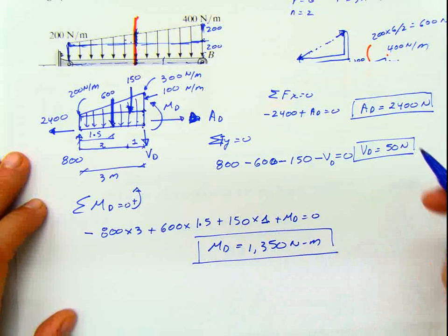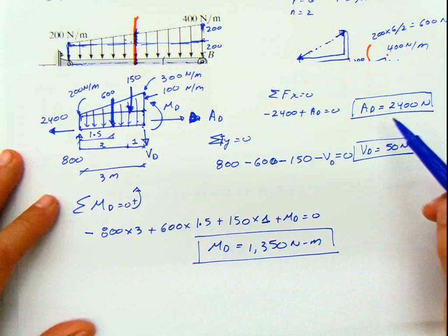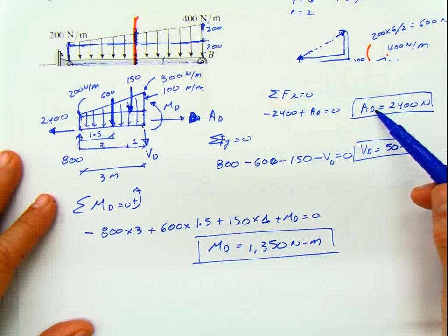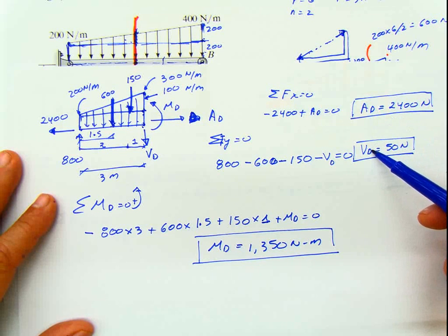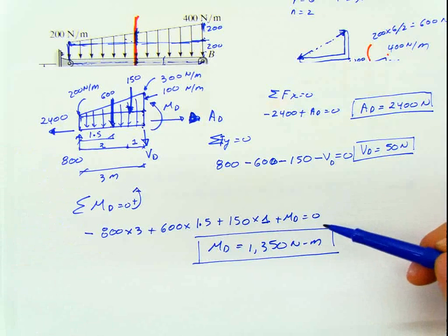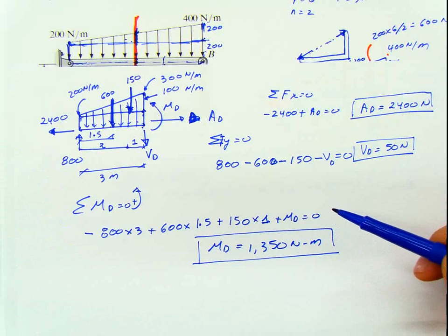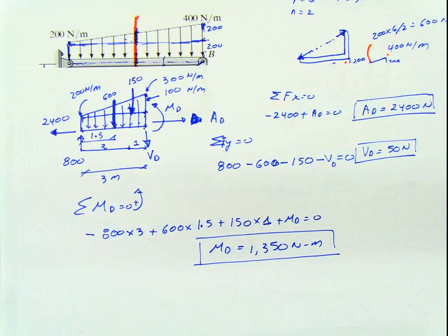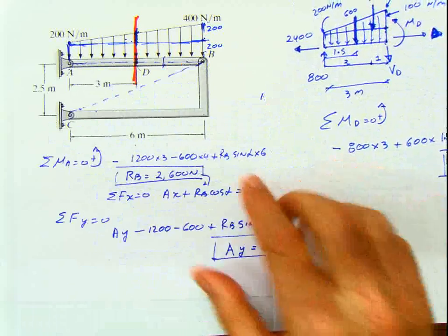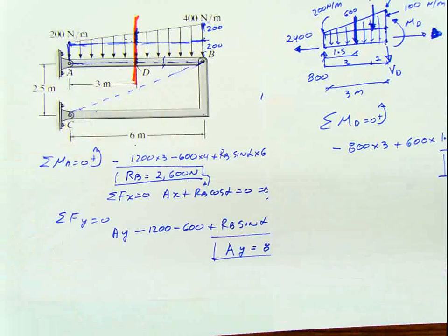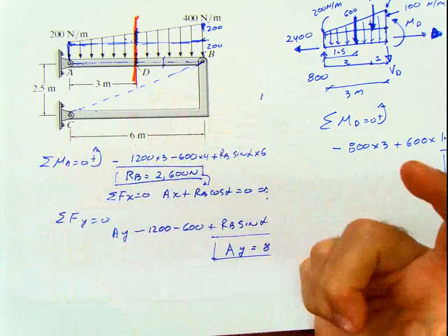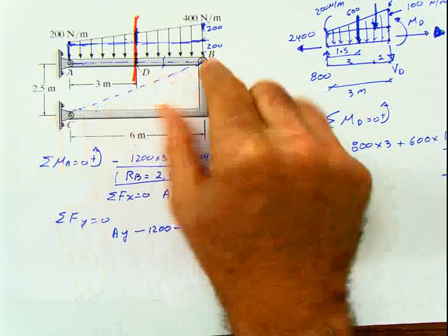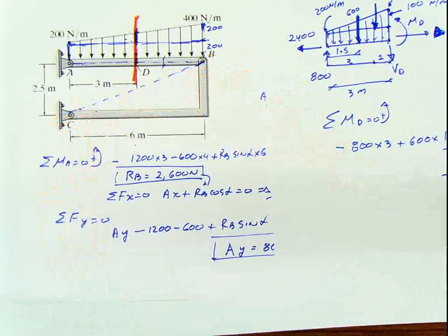So in this way we can calculate our three forces, or three internal reactions, better said, axial at D, shear at D, and this is the moment at D. Usually every problem for every type of situation when you have to calculate internal forces is done always in the same way. You just have to look for a little bit of trick, the little trick that you have to apply in this. Sometimes you don't even have to apply any trick, but that's what I wanted to bring this problem to you, because in this problem the trick is that this is a two force member.